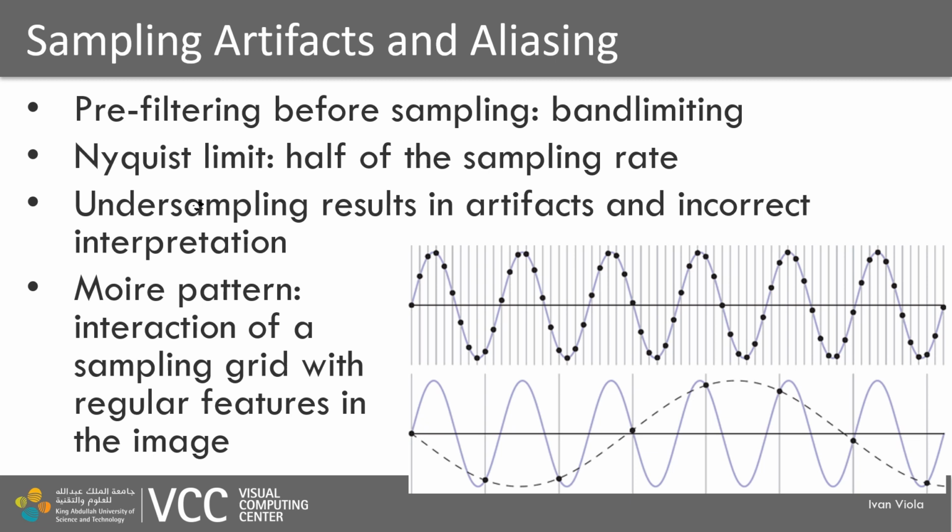And that tells us that if we have a certain signal, which is represented by a set of frequencies, as we will be talking about later in this lecture, then the sampling should be double the highest frequency which is represented in the signal, at least double, so that the signal can be represented or reconstructed from these samples without any artifacts.